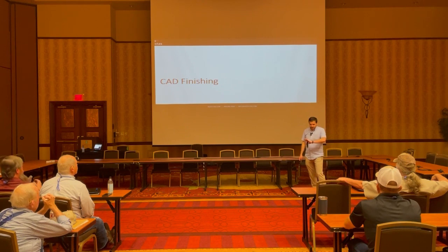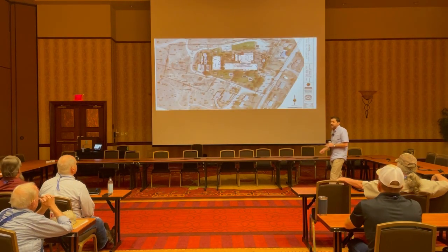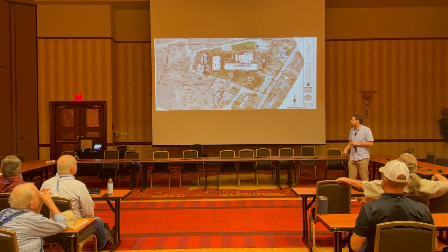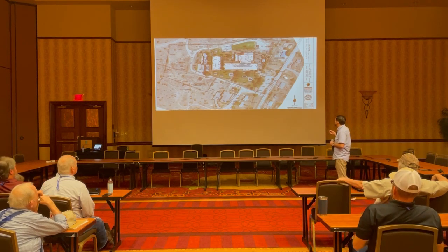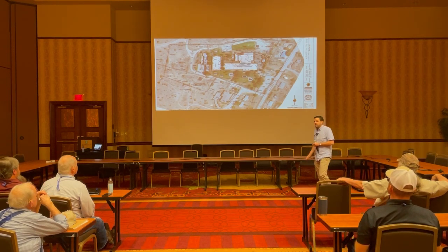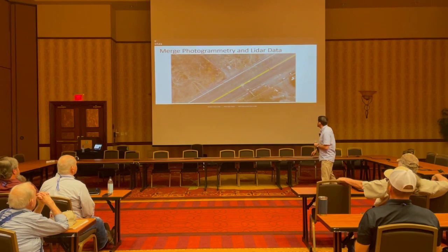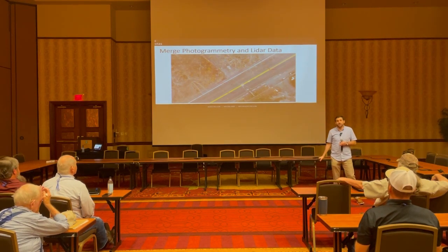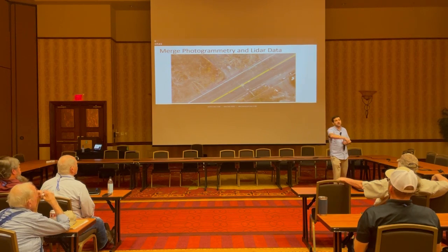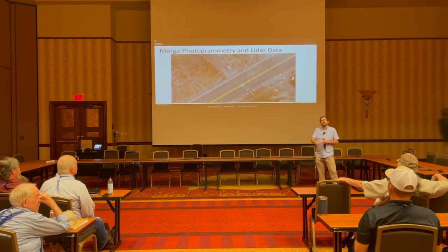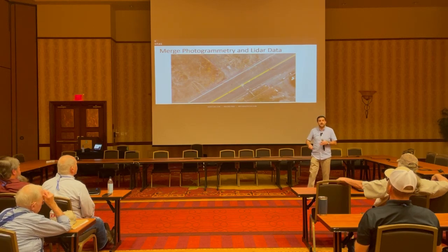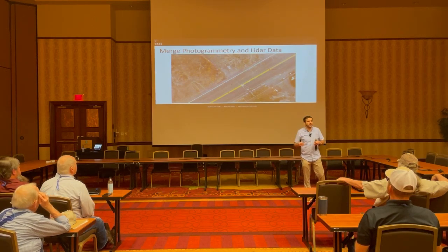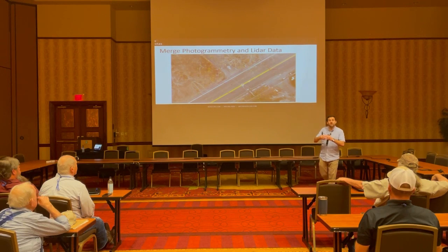All right, and your last step in the process is going to be CAD finishing. That's where you take all of this data that we've processed and turn it into a survey. There are a couple of steps to do that, not too much. Number one is merging your photogrammetry and LiDAR data. If you did what I recommend, extract some data from LiDAR, some from photogrammetry, it is in CAD, all the way at the end of this process, that those finally meet up. If you did your accuracy verification, they'll meet up very nicely.